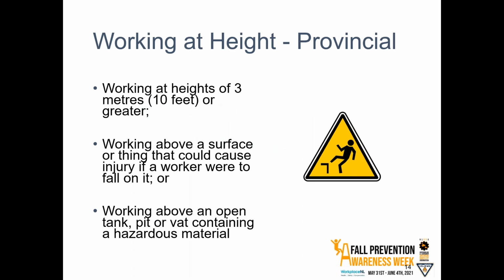So here in the province, we define working at height as working at 3 meters, which is 10 feet or greater, or working above something that if you fell onto it or into it, it could hurt you, or if you're working above an open tank, pit, or vat that contains a hazardous material. So I want to just point out that these are ORs, so it's important to think about all 3 of these. I do find that sometimes when I'm out in the field, people just use the 10-foot rule and they kind of forget about the other 2 items, which are also very important.